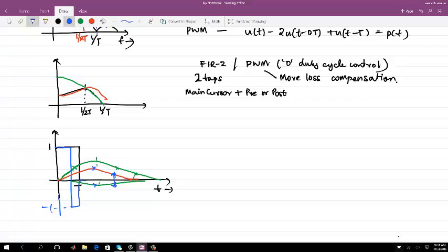If you want to look at a frequency domain picture, you can say that within one period I am having more transitions. Earlier, in one bit period you had only one transition, high to low or low to high. Whereas in this case you have more transitions in a single bit period. More transitions in the same amount of time is equivalent to more high frequency content.